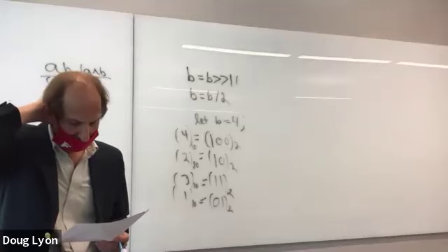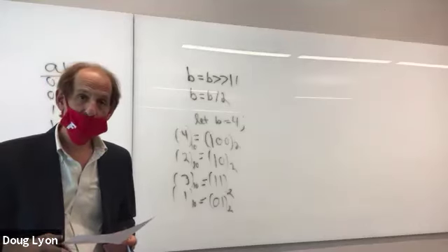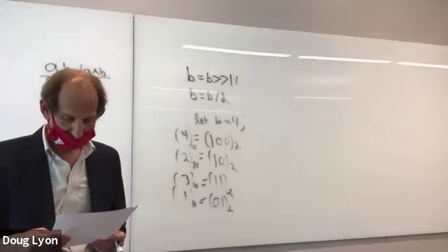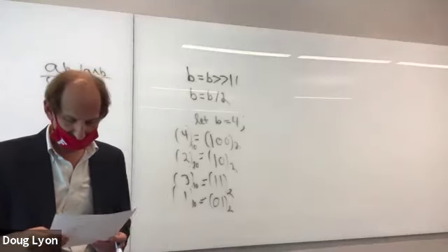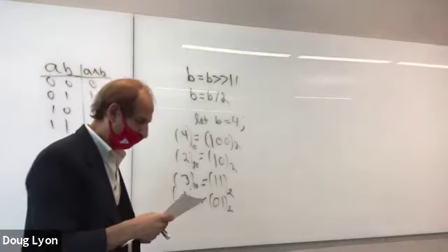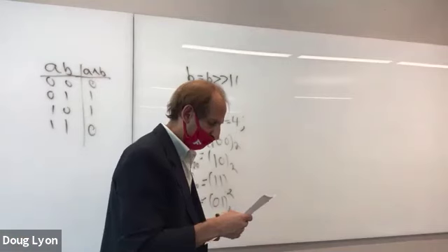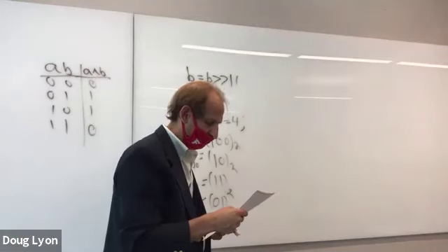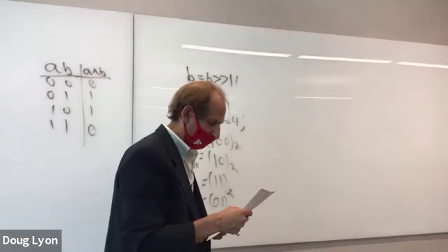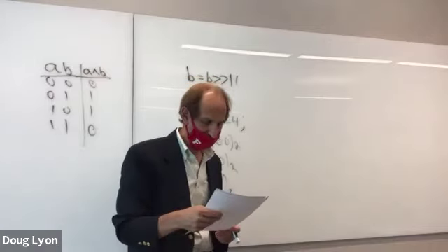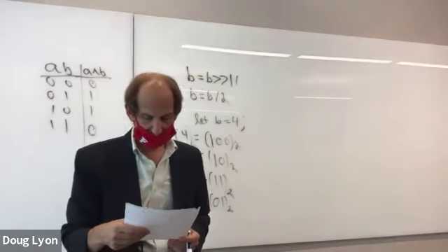Where did I get that number? I think if you do the math, it's supposed to be 5 over 220 because you're applying 5 volts. Yeah, I wonder if I got a typo there. That's 5 over 220. 5 over 220 is not equal to 9 milliamps, but 2 over 220 does. Right. Shouldn't it be more like 5 minus 0.7 divided by 220?